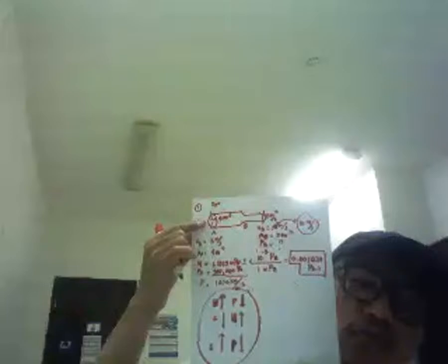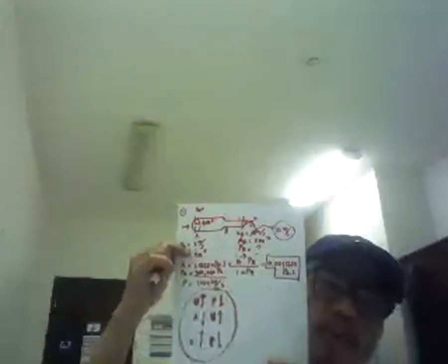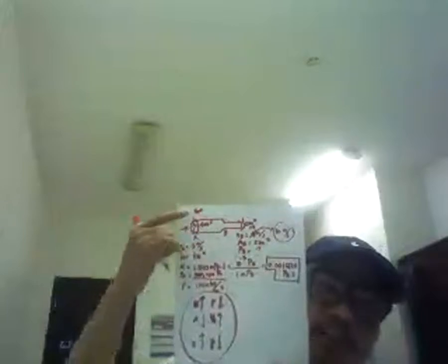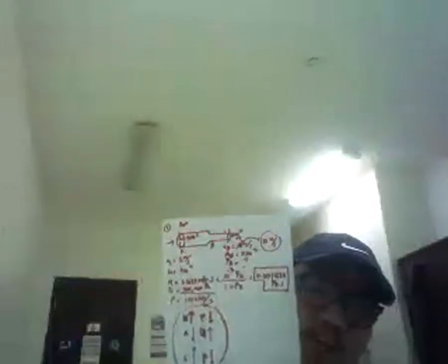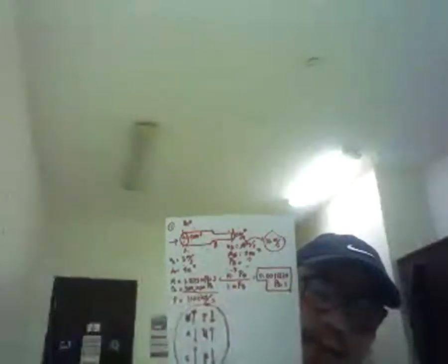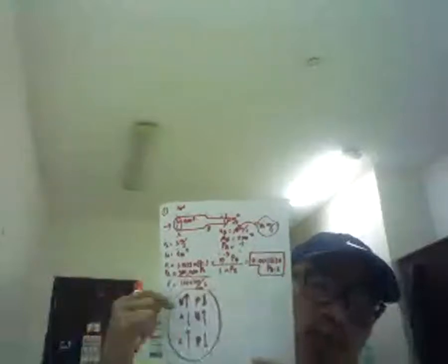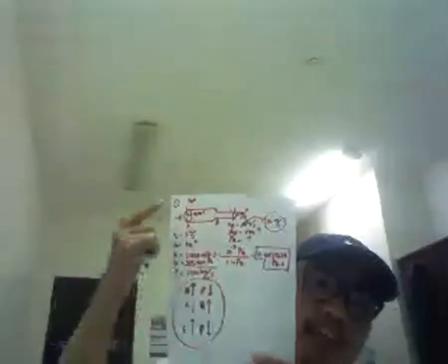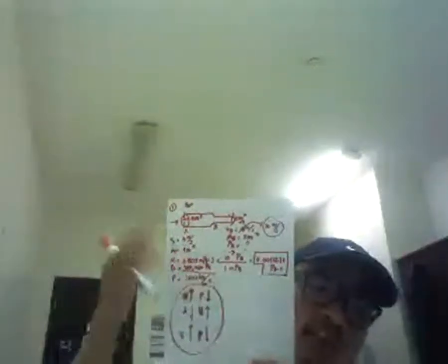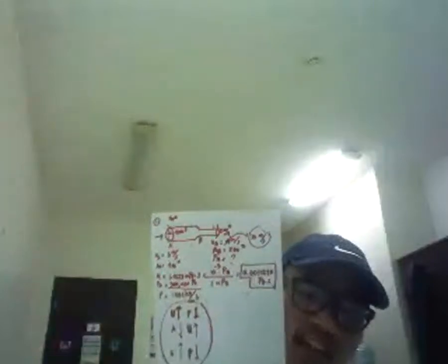So, this is the area in square meters. Area is equal to pi d squared over 4 because this is round in shape. This is the cross-sectional area, pi d squared over 4. You need to account for area 1 and area 2 in getting the Reynolds number, because we are concerned with the diameter at A and the diameter at B, since the area changes.